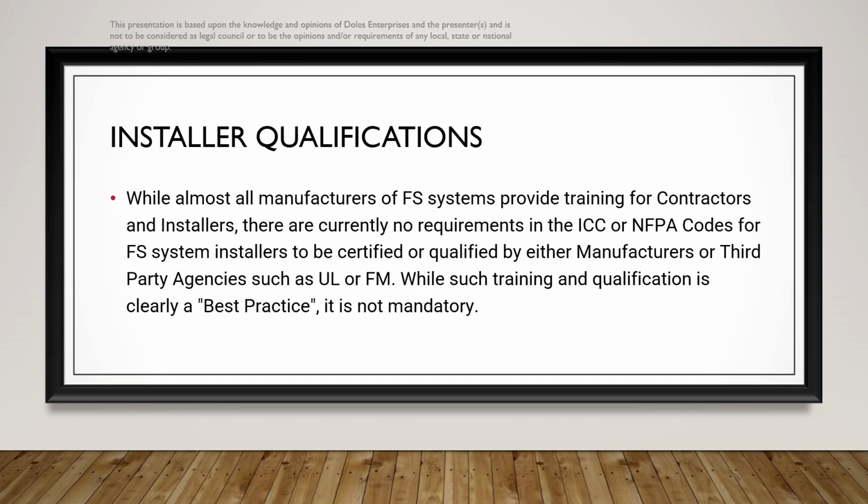Now let's discuss installer qualifications. While almost all manufacturers of Firestop systems provide training for contractors and installers, there are currently no requirements in the ICC or NFPA codes for Firestop system installers to be certified or qualified by either manufacturers or third-party agencies, such as UL or FM. While such training and qualification is clearly a best practice, it is not mandatory.